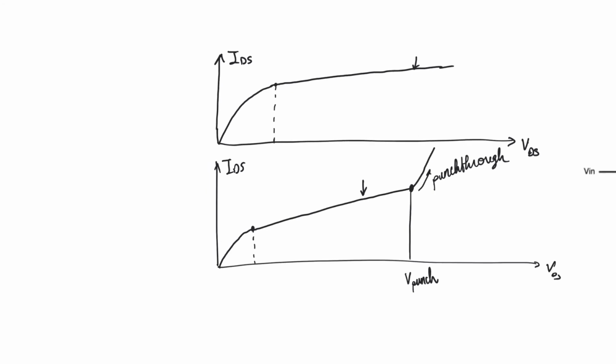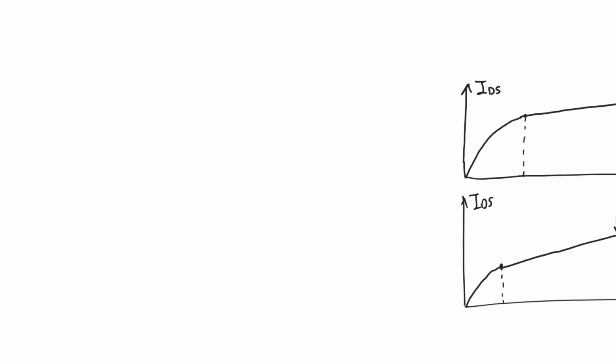If we try to summarize the impacts of scaling on the transistor, we find that we have a much higher channel length modulation. That's one thing. We find that we are dealing with velocity saturation instead of pinch-off saturation, and this leads to two effects.